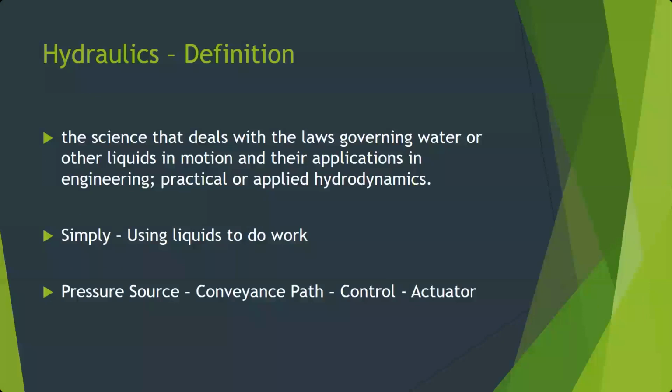And so when looking at them, I talk about the pressure source. Pressure sources can be any number of items, but we've got to take some kind of an energy source and convert it from electrical or mechanical or whatnot to hydraulic pressure. Looking at the various places the pumps are, if we have an engine-driven pump, we're taking energy stored in the form of fuel.